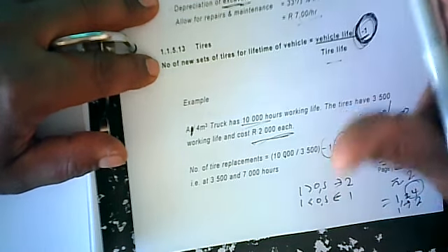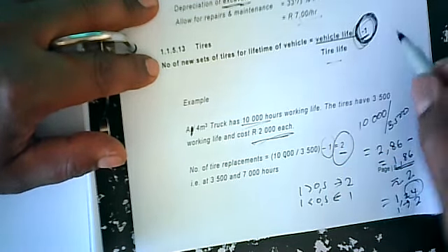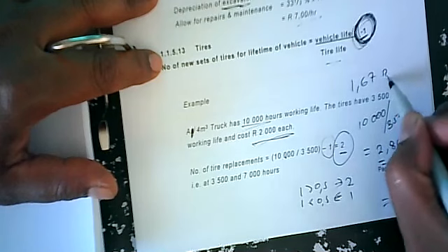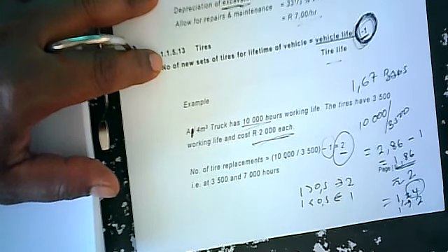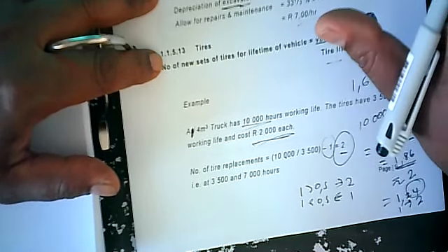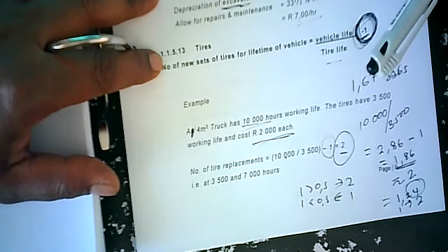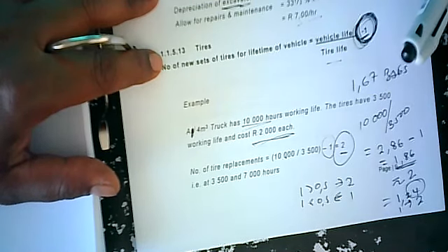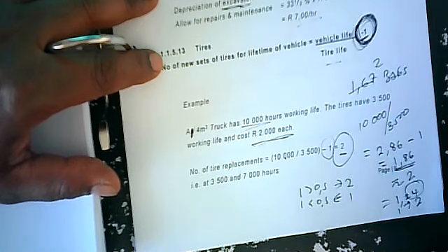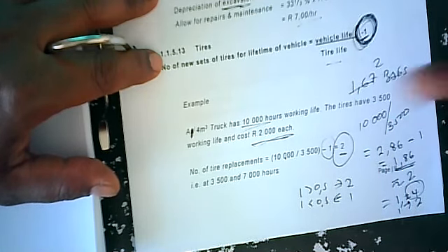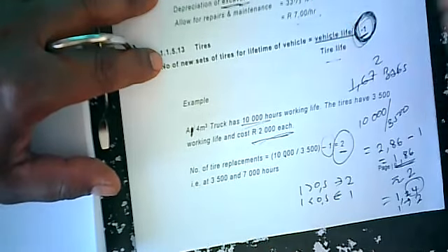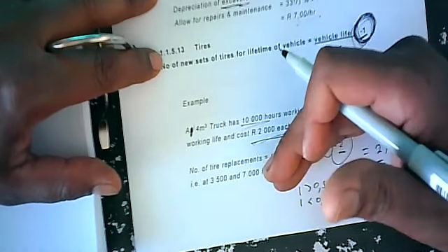You need to be practical here, right? This applies to cement. We'll come to cement calculations in a moment, right? Can you buy 1.67 bags of cement? Can you do it? What is 0.67 bags of cement? I'm sure somebody is going to take out a calculation and divide it by 50 kgs and tell me, right? Now, which hardware store is going to sell you that? All right, they're going to look at you funny. You'll have to buy what? 2 bags. Think of it practically. It's maths, fine, but it's practical maths in the sense of tangible items, cement, tires, cutting discs.